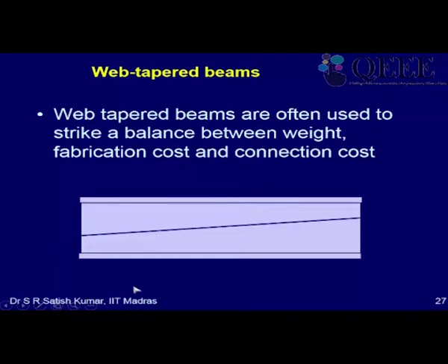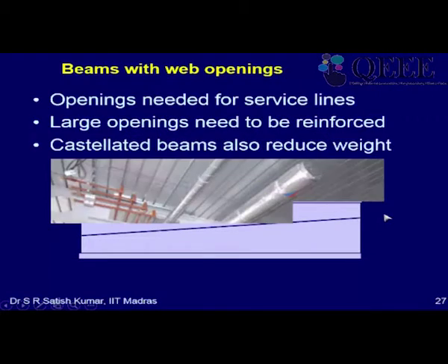So I'll get a very deep beam here and a very shallow beam. This lower depth will come and sit here. So I'll get a tapered beam with a top flange and a bottom flange, which I can use as a cantilever. Okay, with a fixed end at the deeper end. Okay, so that way I can save on steel. So that is also an option.